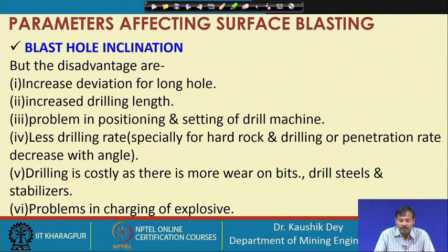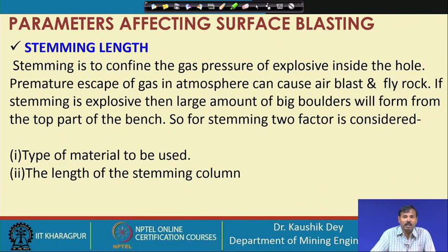Inclined drilling rate is very low, especially for hard rocks, penetration rates are also low, and drilling becomes costly as the wear and tear on the bits and drill steels is more. Often, if we are charging with cartridge explosive, there may be jamming of the explosive in between the drill holes, which may also create a problem. So, these are some problems associated with inclined drilling, and that is why it is often not very preferred in practical mining applications.